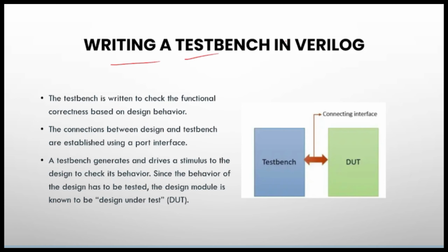Now, writing a test bench in Verilog. How are we going to write a test bench code in Verilog? So what is actually this test bench? In the VLSI design process, in the starting, I have told you that the verification engineer will be sending the input to the DUT. It will be done in the test bench. So the test bench is nothing but an environment where the functional correctness of your design will be checked.